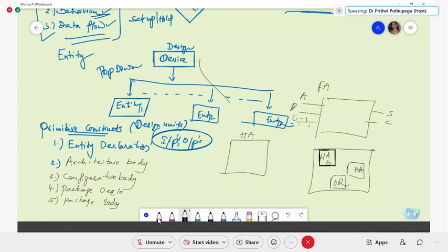So this is one entity, that entity is repeated, and this is the second entity. Each entity you define separately. Now this is the OR entity, and the half adder entity has its own inputs and outputs, your A, B and sum and carry.